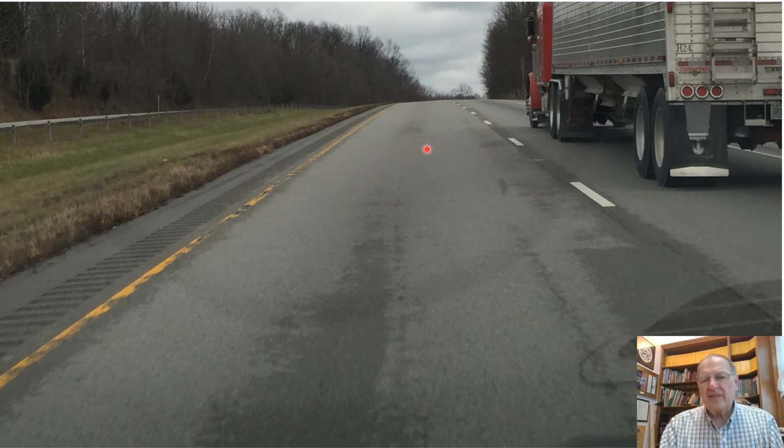Now, I would make the argument to you that in the 75 feet from back at the butt joint up to where my cursor is sitting, there's likely very little change in the mixture properties. It is the same mix. Asphalt content, gradation, all that stuff is the same. What's different about back by the joint and up here where my pointer is? The difference is in-place air voids. So where the air voids are high, the water can get in and aging can happen.